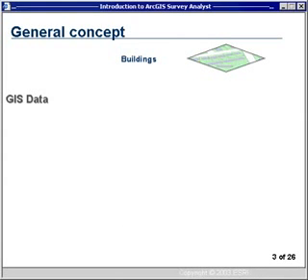So what I want to do now is take a look at the buildings layer. In this configuration, we have a theme called buildings. I have a layer called buildings. And when I operate on that in terms of editing or adding features or adjusting features, I'm going to work on a feature level. So I've identified a building, for instance, that I've selected from that layer that I want to perform operations on. Now, that building or that feature has coordinates, and those coordinates define the location or the corners of that feature. So here you see the red dots at the corners of the building, for instance.